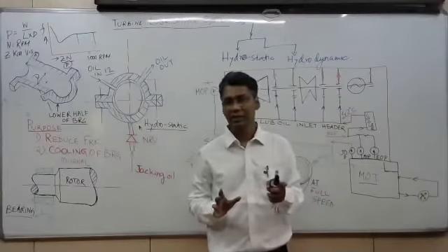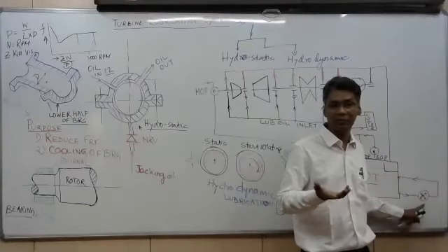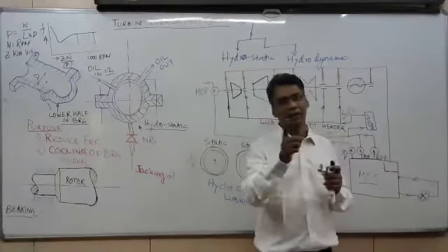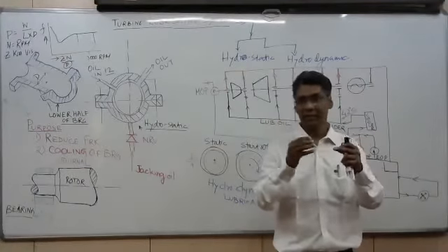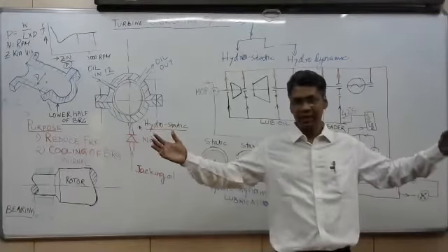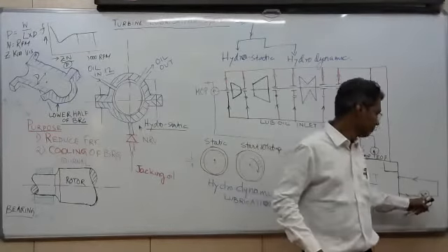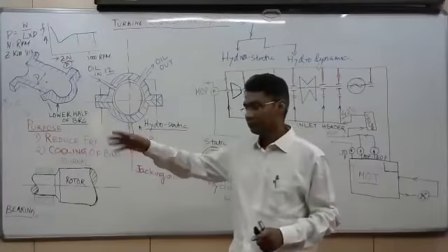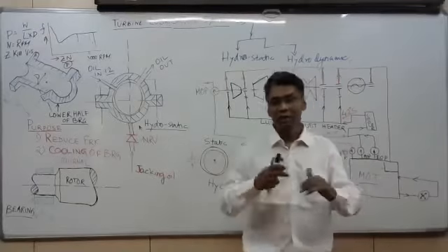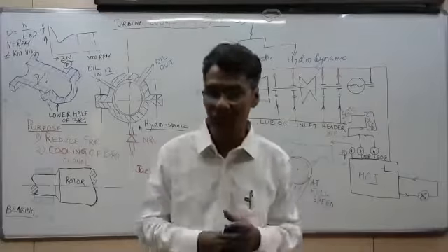It is not running continuously; sometimes, when required, it will run. The centrifuge runs at high RPM, around 9,000 to 10,000 RPM, rotating the oil. It is a very simplified method. As you know, oil is lighter than water particles, so the water particles move away from the center, and in the center the oil flows, and they are separated. By this means we can separate mainly the moisture from the oil, because with continuous moisture contamination, the oil's properties will be damaged.